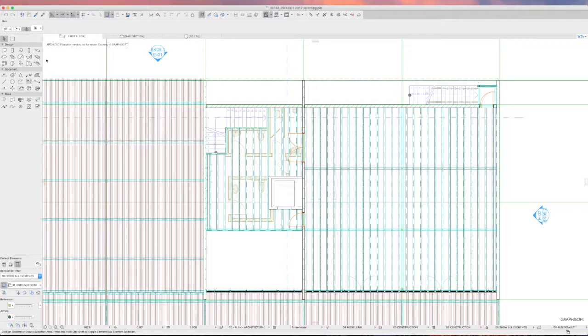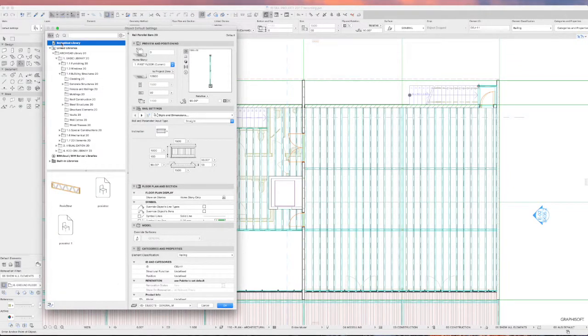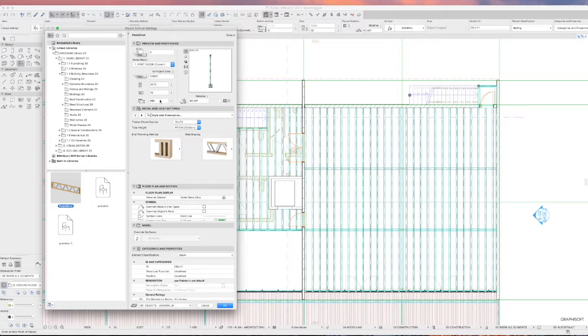But after you've done that, you should find that you'll be able to go to the object tool, and in your object tool it will now be in your embedded library, and in your embedded library you should now have a Posi Strut. And you can now change your timber chord sections to Australian sizes, and you can also change the heights, even though there's another parameter somewhere I should have changed for the height code name. But if you change your height here with this flyout, you'll see the standard sizes that we typed in there are now available, and you can change to those standard sizes.